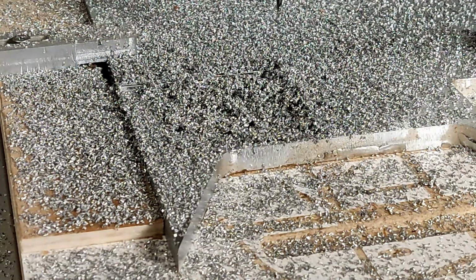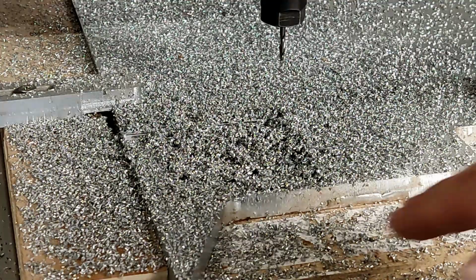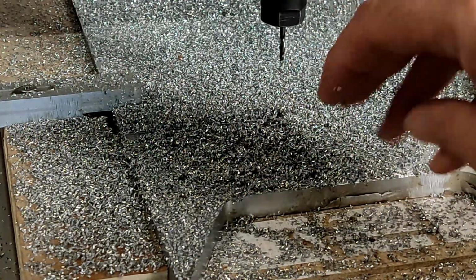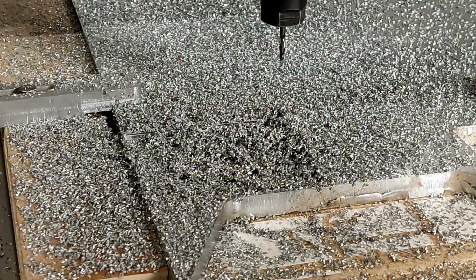Well, I have to admit I didn't expect it to work so well. Now I will try to find a way to clean this mess up. The toolbit is cold, it didn't heat up at all. Probably the aluminum plate is just barely at room temperature, so having a toolbit that cuts as it should is essential. You have seen what happened to the first toolbit, the one that didn't cut well. It heated up, it melted the aluminum and broke after just a couple of millimeters.